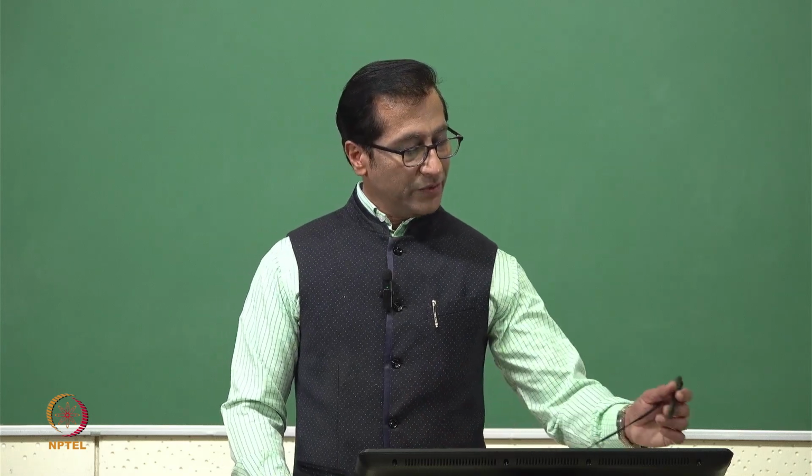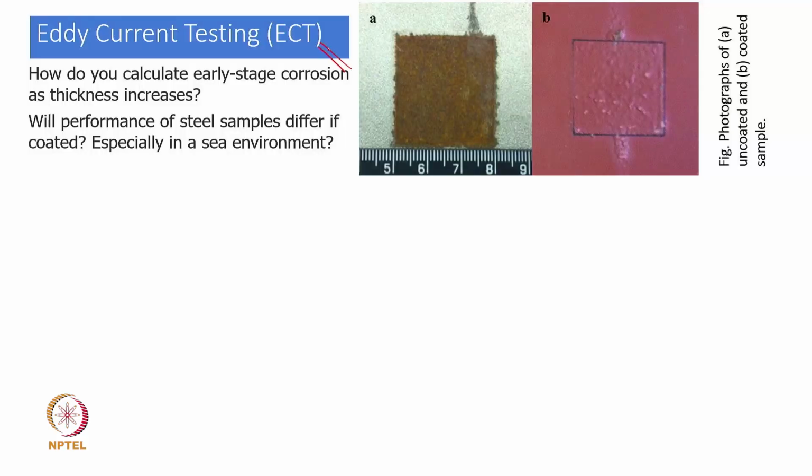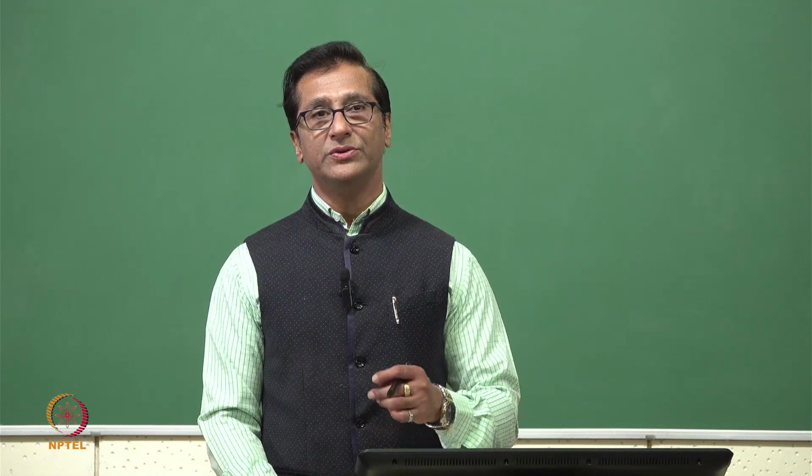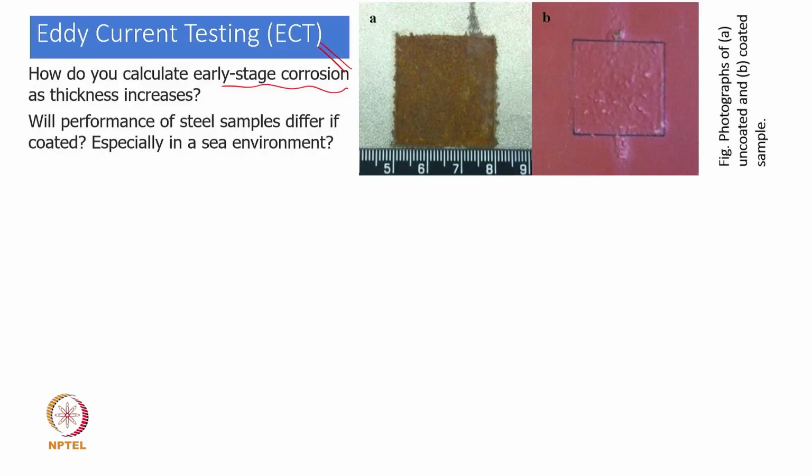Now, when we go for the eddy current testing, it was also mentioned very clearly how we test particularly the early stage of the corrosion. Here this is where we are talking about the new testing. Of course, radiography is one of the tests, but there is another test we call the eddy current test. We say that with an increase in thickness, what kind of response will be different.